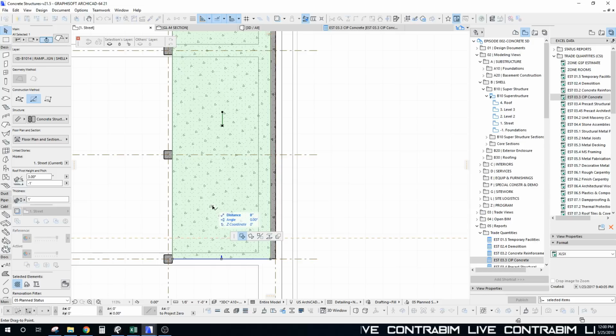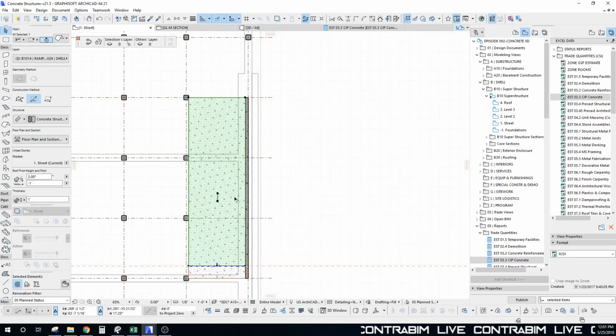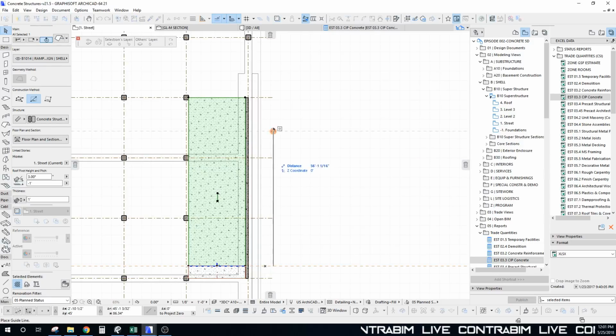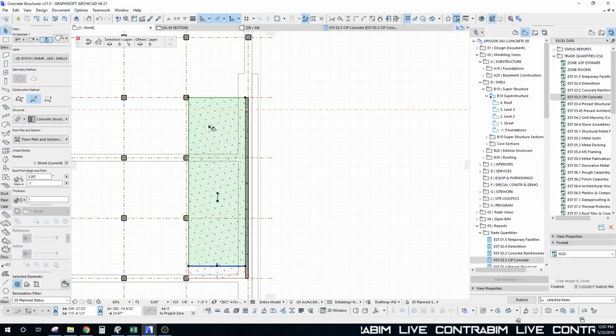And I'm going to take this and split this element, and move that working point right there. Then I'll do the same thing on the other side: we'll pull this over, and instead of going 75 feet, if I go 65 feet, that puts it 5 feet off there, and we'll split that again, and then just move our pivot point over.